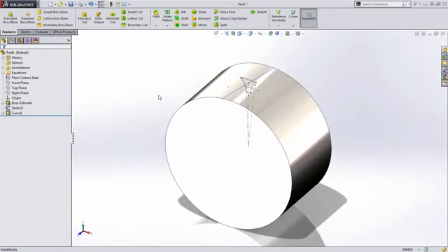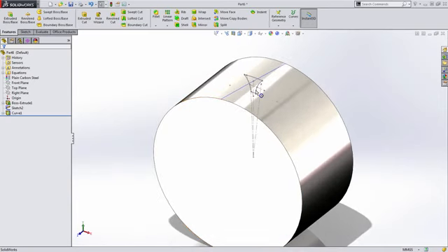Now at this point, you'll see a lot of videos where they try to do things such as twisting the geometry or sweeps, or they'll calculate this, but by using a few simple features, I'm letting Solidworks do the work for me. The last thing we need to do to be able to create a cut loft is we need this profile on the front of the part and on the back of the part.